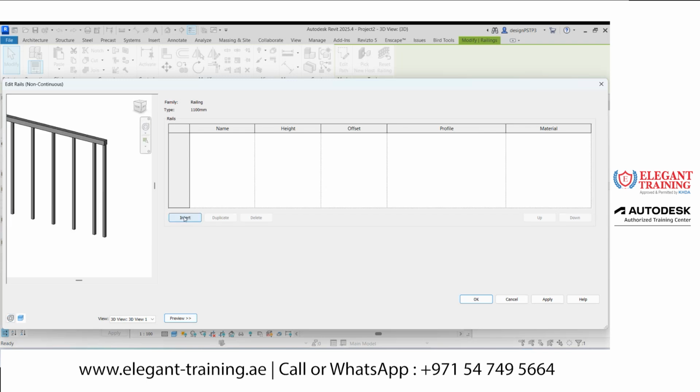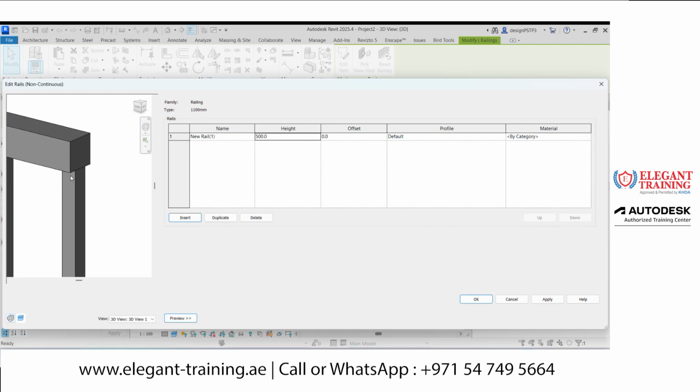If I'm inserting one rail, and I have given this one as a new rail, and the height I'm giving here is like 500, and the profile, so it's made up of the profile. See, profile means only the 2D shape. We will make the 2D shape, and wherever I'm sketching this railing, that profile will automatically create a sweep.